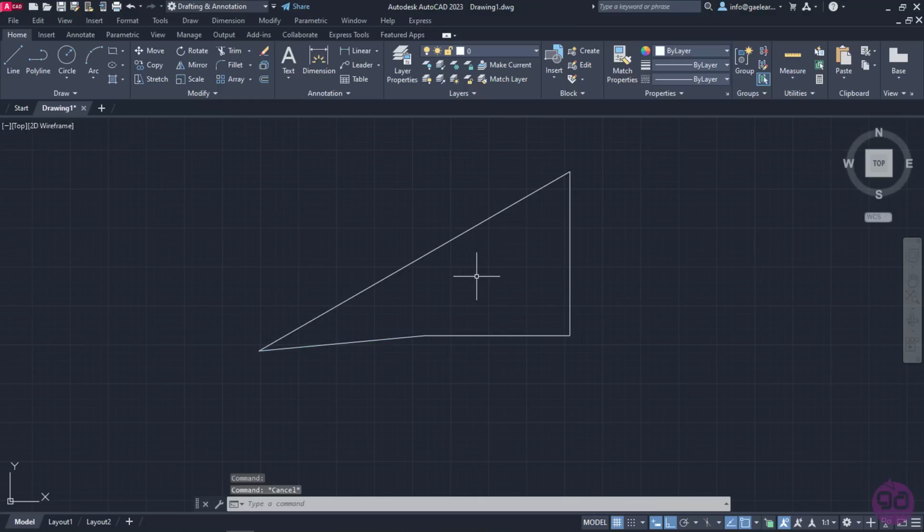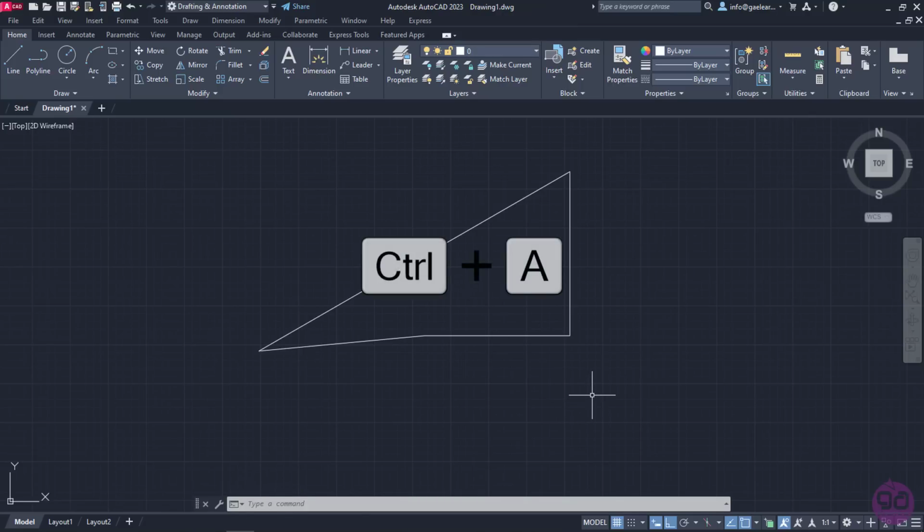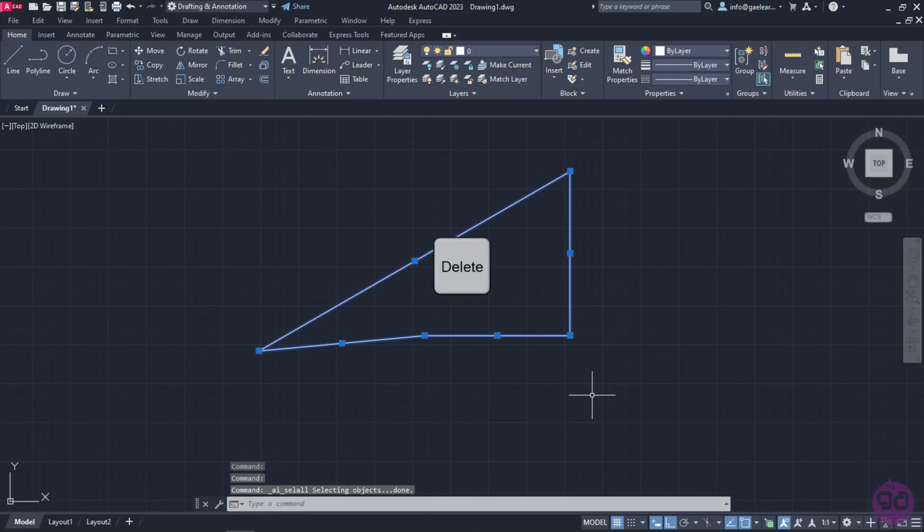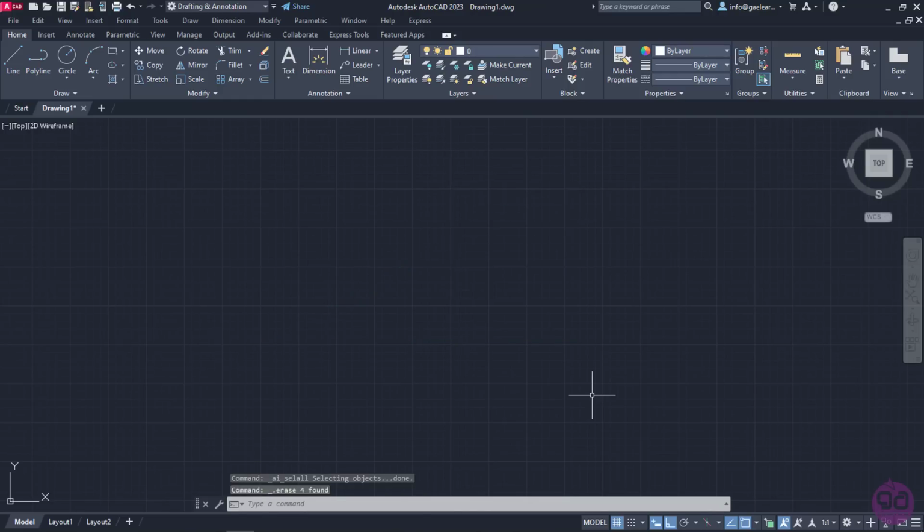However, what happens when I want to create lines of certain length and angle? I will select the lines I previously drew and press Delete from my keyboard to delete them. I will also deactivate ortho mode so I can move the cursor freely again. Imagine now that I want to create a line that is 5 meters long at an angle of 35 decimal degrees. I will activate the line tool again and I will click to define the first point in a random place.